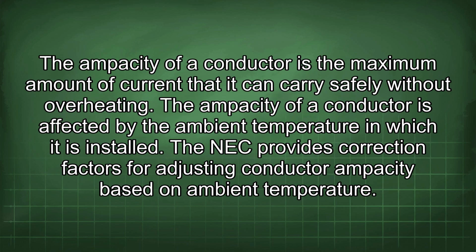The ampacity of a conductor is the maximum amount of current that it can carry safely without overheating. The ampacity of a conductor is affected by the ambient temperature in which it is installed. The NEC provides correction factors for adjusting conductor ampacity based on ambient temperature.